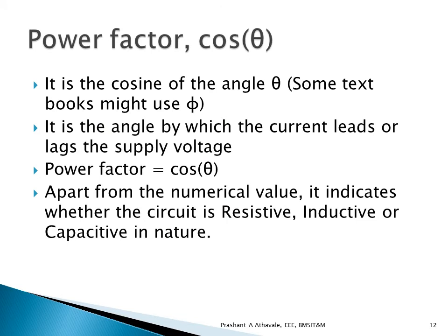So this is the power triangle. Continuing with the power factor itself, it is the cosine of the angle theta. Whenever we are solving these numericals, we will discuss the power factor further. We have also written here that textbooks use theta or phi or other symbols, so whichever textbook you are following, feel free to use that nomenclature. So what is that theta? Theta is the angle by which the current is leading or lagging the supply voltage.